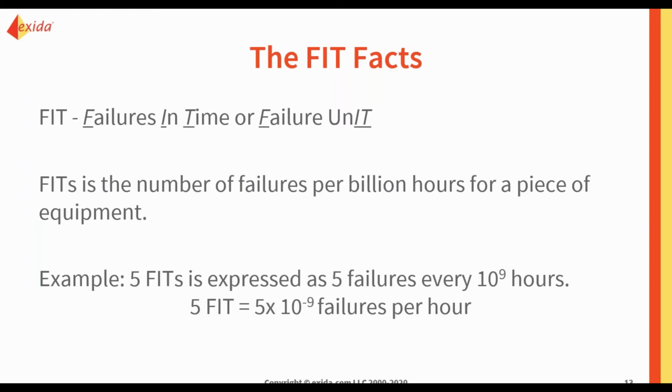They go into very significant end user equations such as your PFD average or PFH calculations and other SIL verification tasks. So it's absolutely imperative that they are not only right for your application, your operation, your demand, and your environment, but they're also realistic and correct.